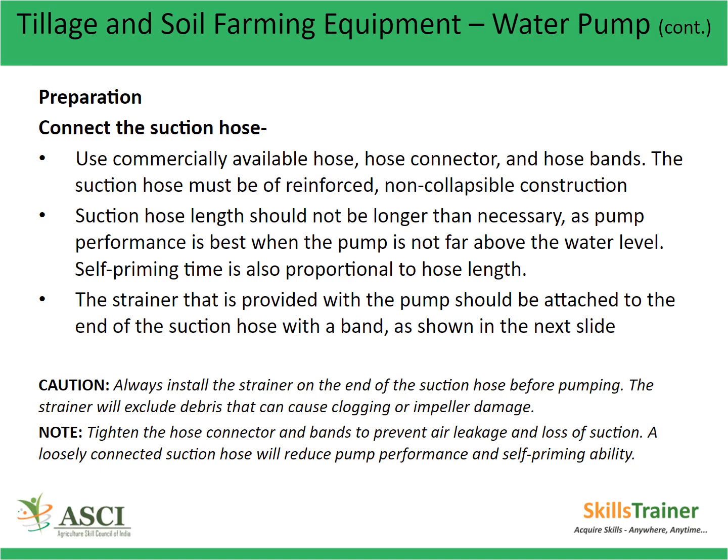Preparation. Connect the suction hose. Use commercially available hose, hose connector and hose bands. The suction hose must be of reinforced and non-collapsible construction. Suction hose length should not be longer than necessary as pump performance is best when the pump is not far above the water level. Self-priming time is also proportional to hose length.